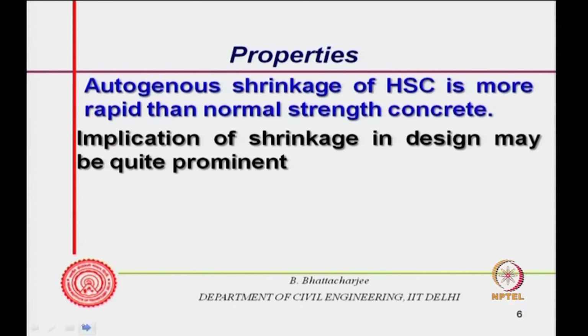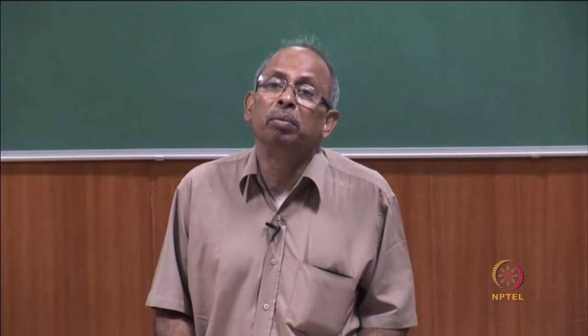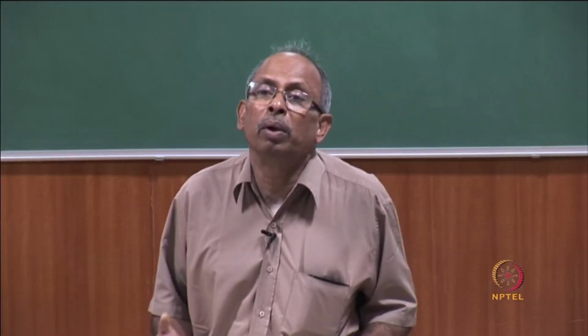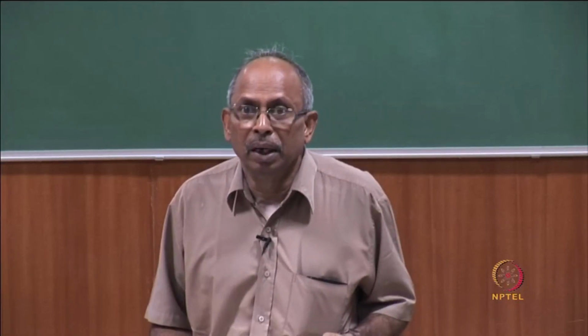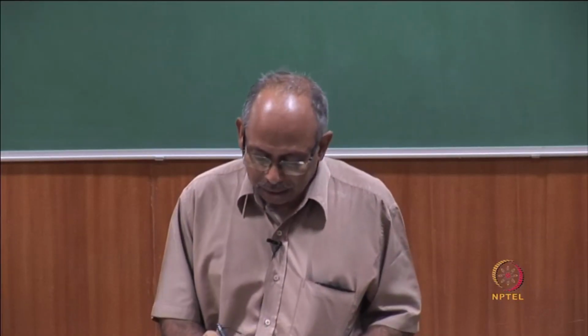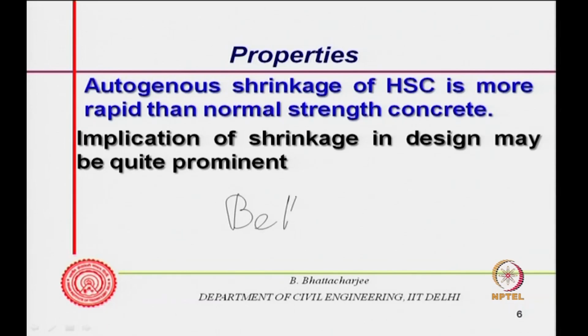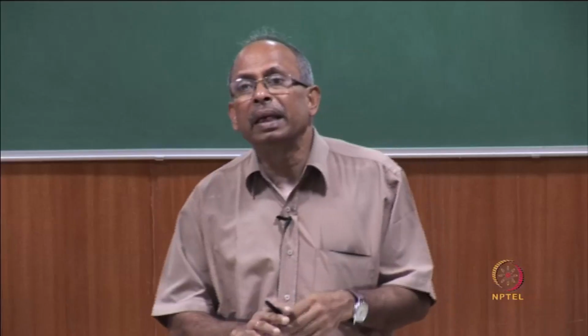strength concrete. Of course, it has implications in the design, and the design implication could be quite prominent. Now, you must understand that high strength concrete is not used in all structures. High performance concrete, you may not use in all structures. In the last class we saw that it has better durability. So you might be using high strength concrete or high performance concrete simply from the durability point of view, because it is a dense structure.